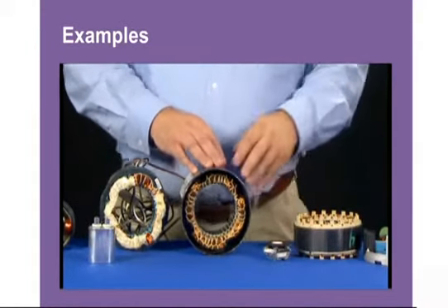The most efficient motor in the market is a three-phase motor. These motors have 3 sets of windings that pull on the rotor, making them one of the more efficient motors in the market. One of the easy ways to identify a three-phase motor is the number of leads exiting from the motor, either 9 or 12 wire configuration. These are typically in a commercial application.